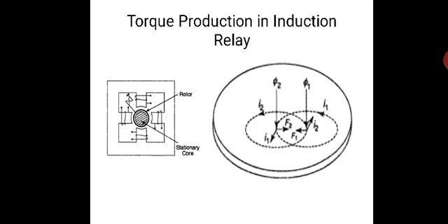In electromagnetic induction, the disc relay operates on the principle of an induction motor and is widely used for protective relaying purposes involving AC quantities. They are not used with DC quantities owing to the principle of operation. An induction relay essentially consists of a pivoted aluminum disc placed in two differing magnetic fields of the same frequency but displaced in time and space. The torque produced in the disc is by the interaction of one of the magnetic fields with the current induced in the disc